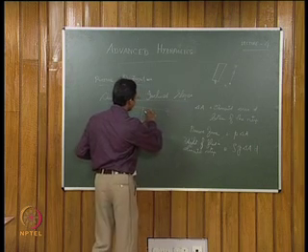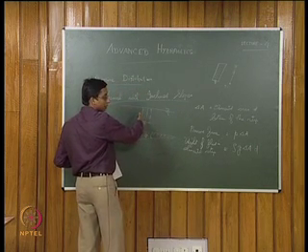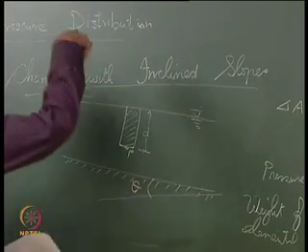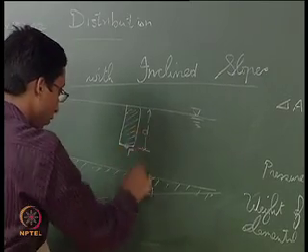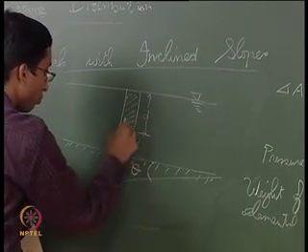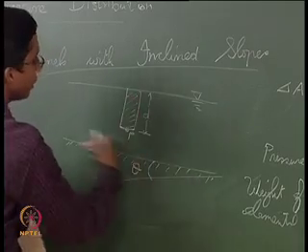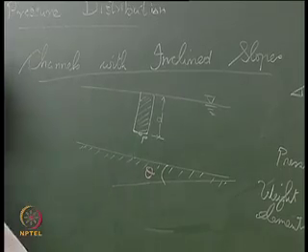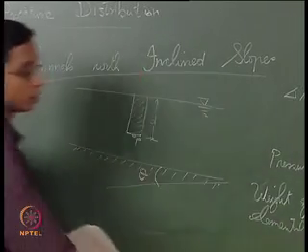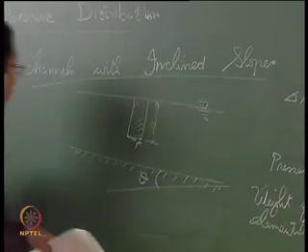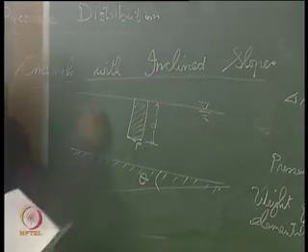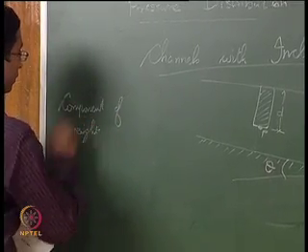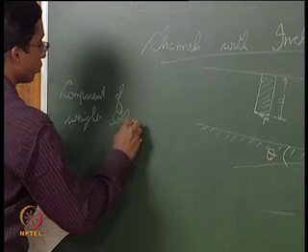Now, you cannot directly balance both, because the weight of the fluid acts in the vertical direction, whereas your pressure force is normal to the bed, which is already inclined at an angle theta with the horizontal. So, you cannot directly balance it, you need to take the component appropriately. The component of weight balances the pressure force.